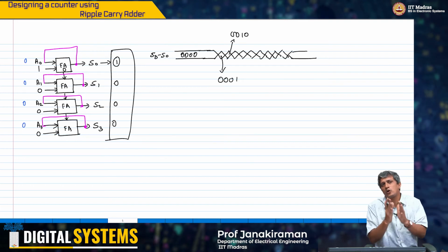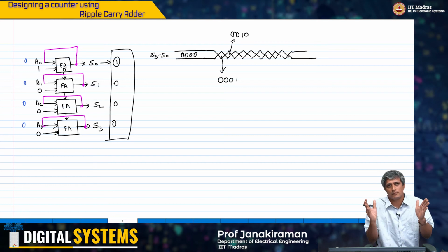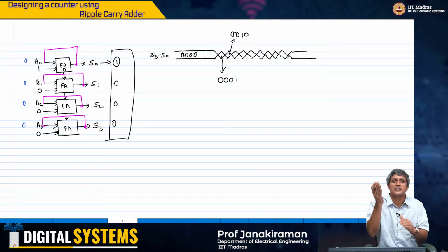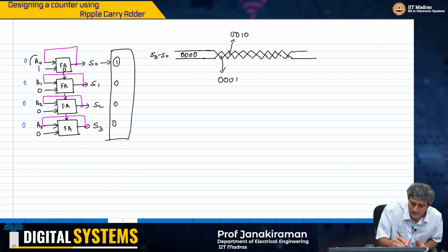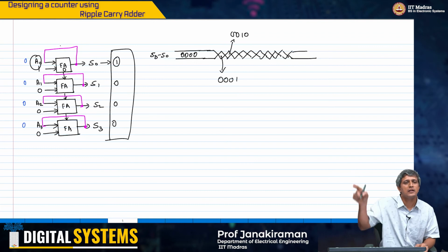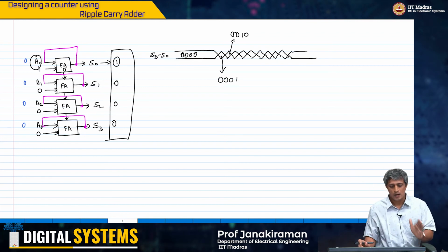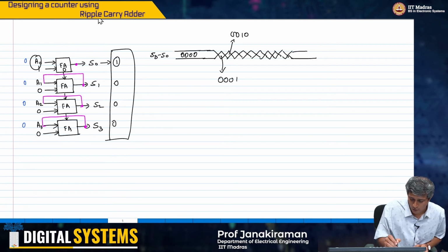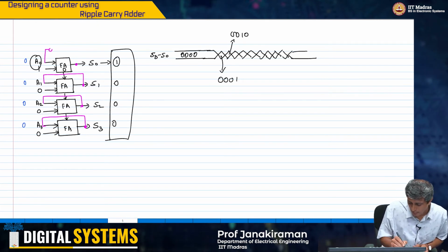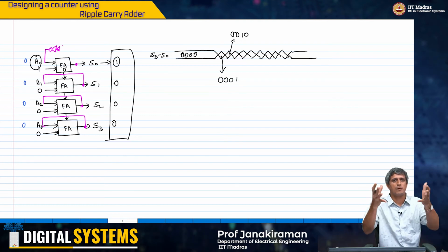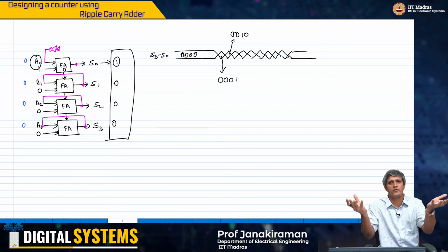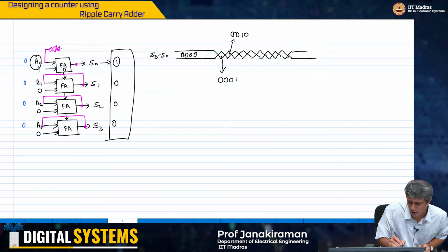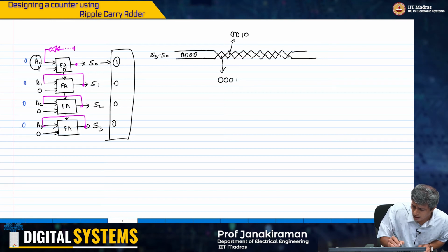In some sense, I want to control the time. Okay, I need to control when the state changes at these A's, and therefore it is not okay to simply feed back the output just like that, right? Now you could argue that I could just add delays here. For example, instead of just feeding back, I will add, okay, these two inverters are basically a buffer. Logically there's no inversion happening. If I put two back-to-back inverters, I'll put an even number of inverters, a large number of buffers